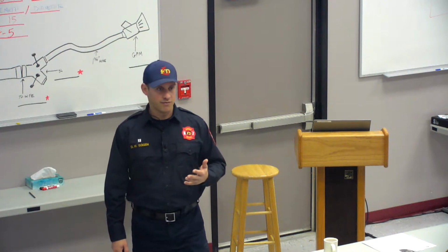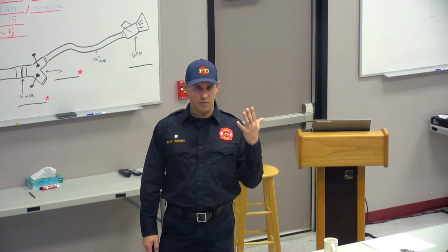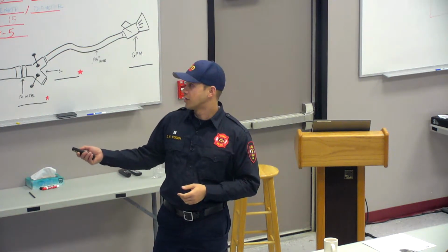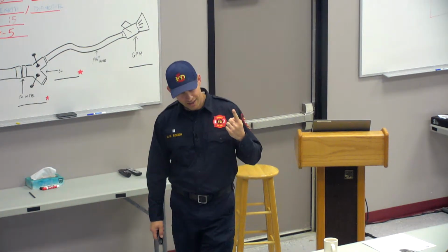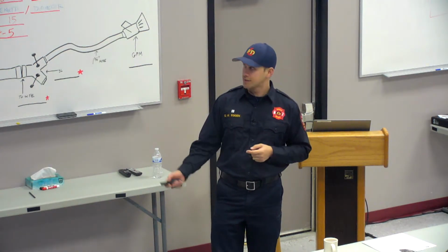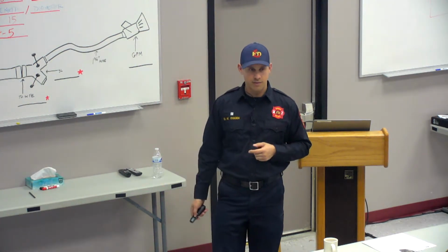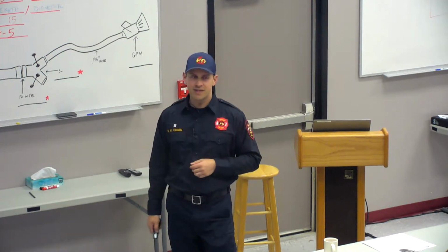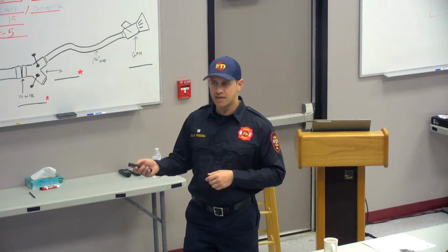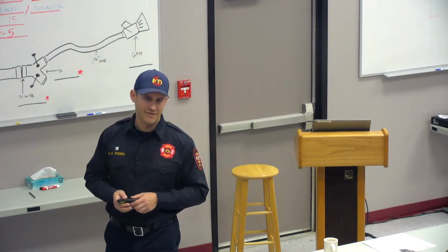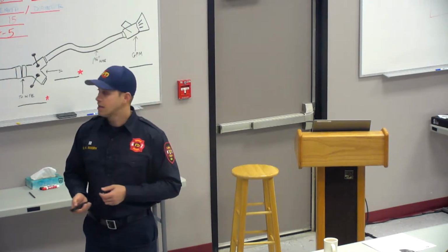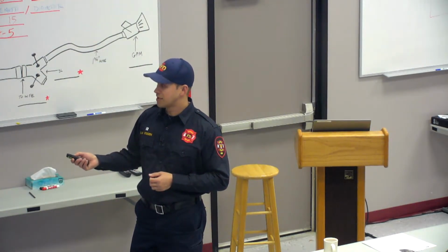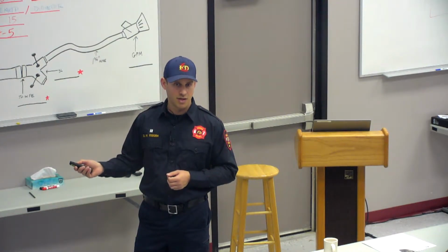So let's say we're flowing 500 gallons per minute. I'll remove the 100. I say 5 times 5 is, you get 25. If I'm flowing 100 gallons per minute, 1 times 1 is 1. Now when I get in these 150s, the 250s, the 350s, I'll round up. Because the reality is you're not going to notice the difference of 5 to 7 psi on that tip. That will get you in a very close range. There's very little difference in 21 psi and 25 psi on that nozzle.